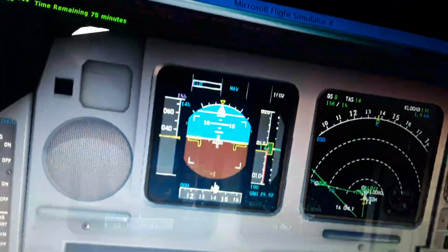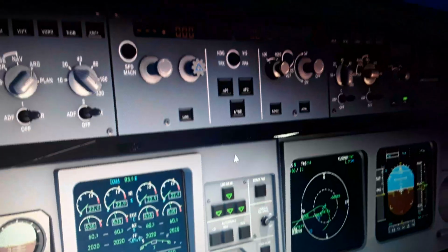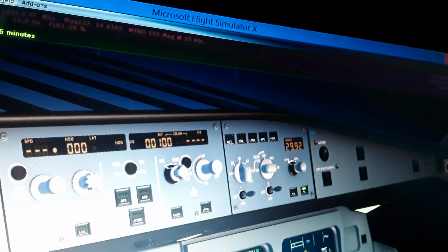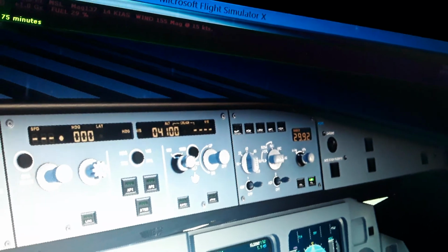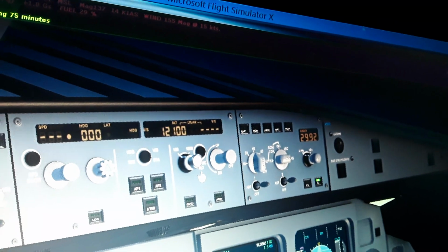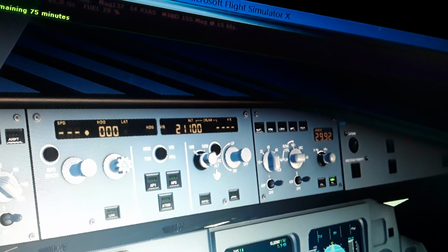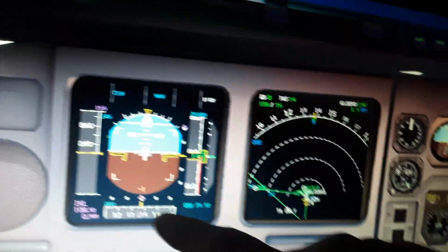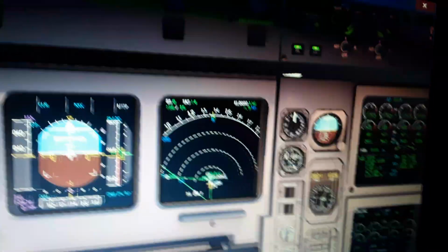So here is so much for the flight plan. We're ready almost to take off. We only need to set the flight altitude. And turn the ILS on, which is going to arm here in the runway heading. So we're ready to take off right now.